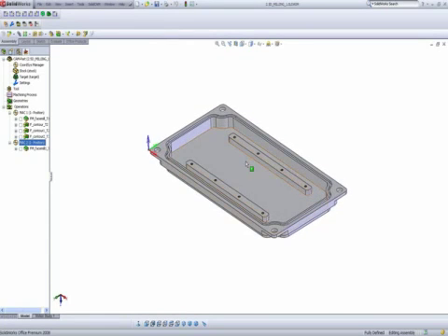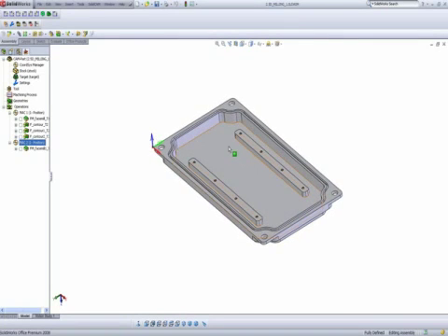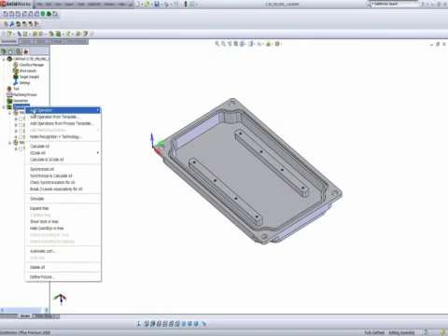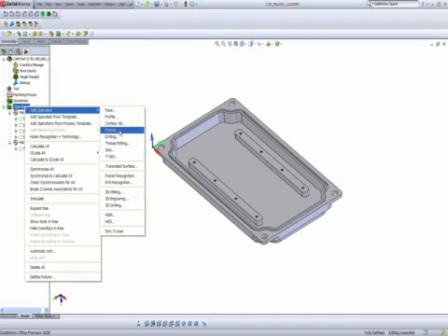So what I'd like to do in this particular part is first mill out a pocket from the upper level over here up until the height of this particular island, and then do another pocket operation from this height of the island all the way down to the floor, and then including the operation of the islands. I'll start my operation by adding operation of pocket.